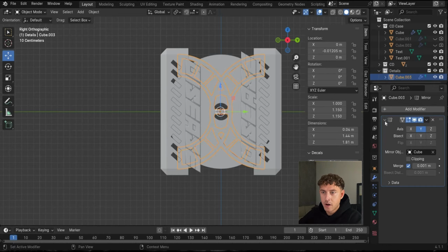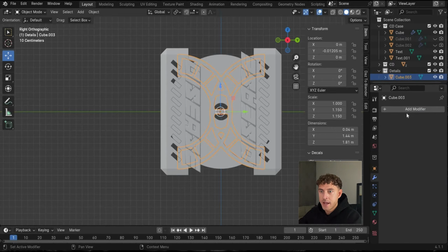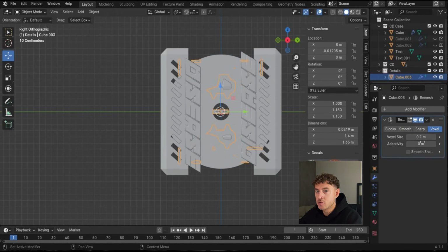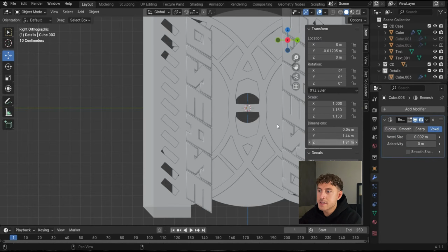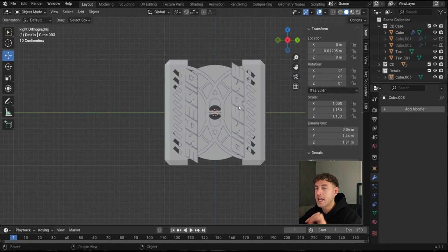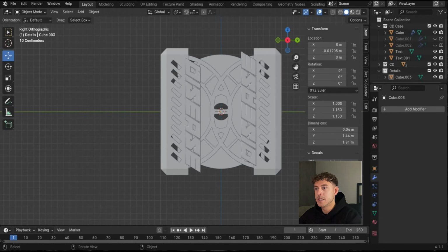I did the project before. The thing is that when we work with glass and we have two overlapping objects, Blender doesn't recognize the matching points, and where the connection points are, there will be black holes created. So now we apply the mirror modifier, and to avoid this problem later on, we have to use the remesh tool so that we get one single object and Blender recognizes, okay, it's one object remeshed and we don't have the issues later on. Choose a voxel size that fits. That looks good. Apply the effect, and later on we won't have any problems in the material part.